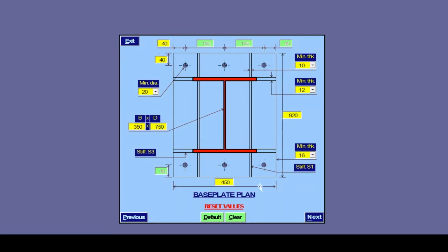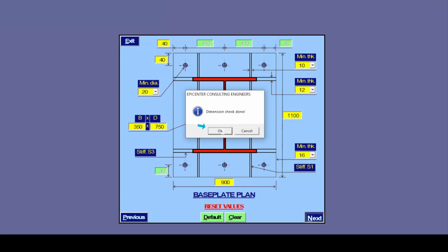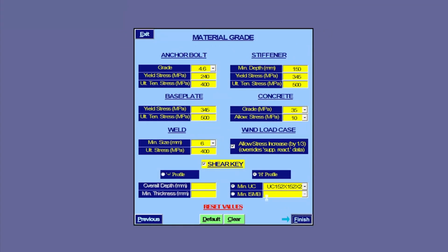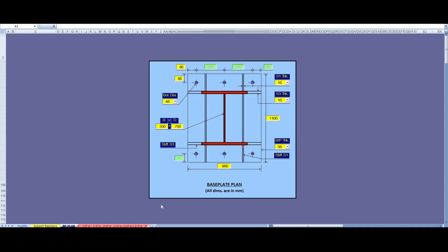Fine, we increase the width to, say, 900 mm, and length to, say, 1100 mm. And this completes the baseplate design. Design with BP8 type requires 48 dia bolts. If the project calls for lesser diameter for some reason, this is what we can do.